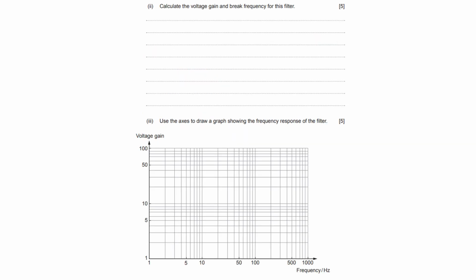Okay, from the previous page, it was a bass cut filter, by the way. So it was one of those jobbies. Easy, isn't it? If it's in series, it's a bass type filter. So bass cut is that one. If you put it in series with the feedback, it's a bass boost. And then it's the opposite for the treble. So you put the treble in parallel with the feedback.